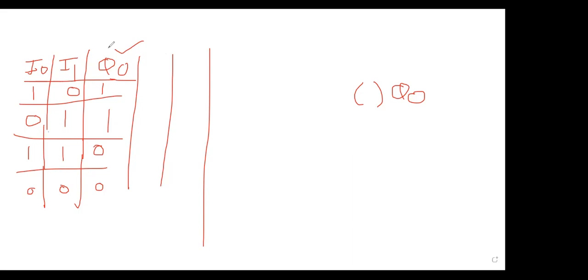Let me show you on screen. Make a truth table, go to the first output, take a coil, check the true condition. Where is it true? Here it is, isn't it? Q0 is true here, on here. So when Q0 is on, what is the status of inputs? Inputs are 1, 0, isn't it? So when Q0 is 1, the inputs are 1, 0. For input 1, you take NO. For input 0, you take NC. I know it's complicated. Now I shall show you practically on screen and it will be very much clear. So don't note down, look at this, how you can make this easily.